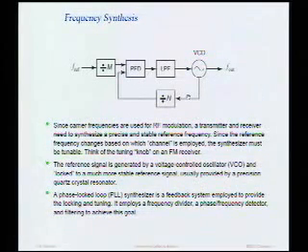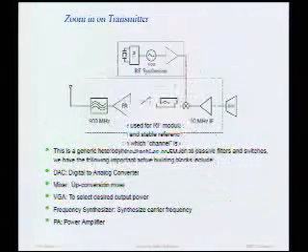In particular, we'll look at how you build a frequency divider, how you build a phase detector or a phase frequency detector, and basically this is a low-pass filter. I assume you know how to build a low-pass filter. But we'll talk about how you stabilize this feedback system. It's actually an acute feedback system because it involves a lot of nonlinear components. And we'll find that we can linearize this system over a small range and analyze it as if it were a linear circuit. So we'll talk about that also later.